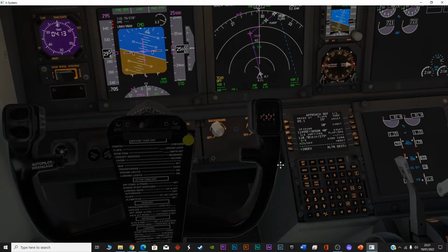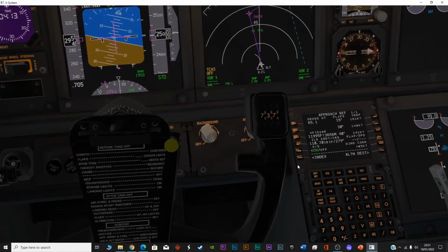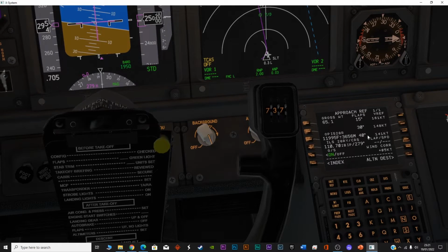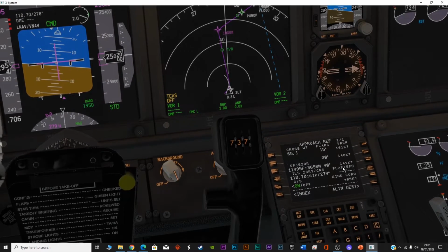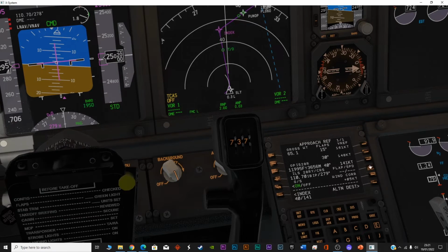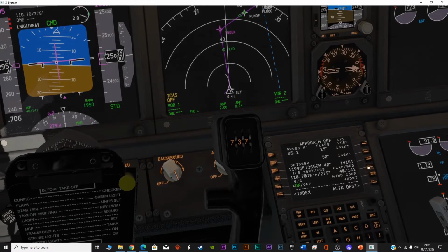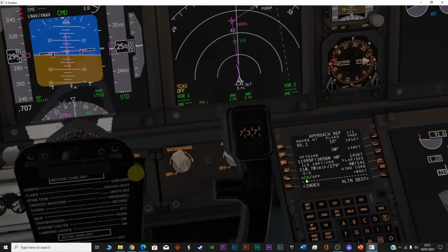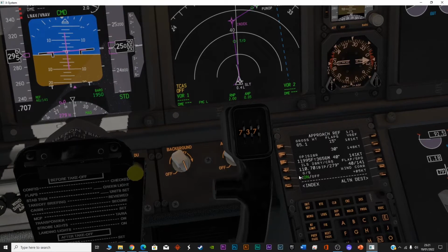Approach, you can see during the approach some settings. 40 flaps, if I go with the full flap landing, the speed should be 141 knots. So I'll just copy it, and you will see it is copied, and I will paste it over here. Okay. So now the glide slope is on. We will see the glide slope, and that's it.